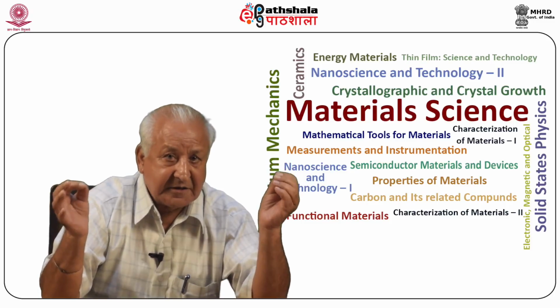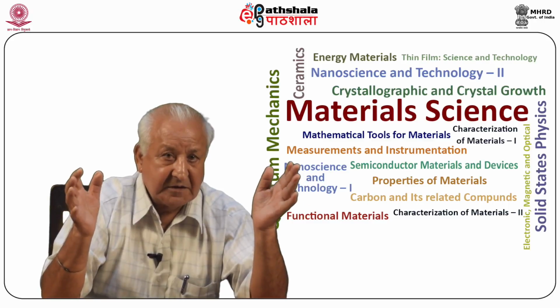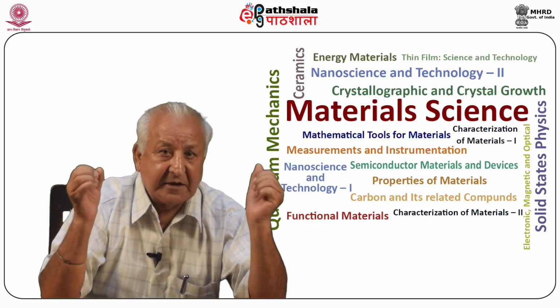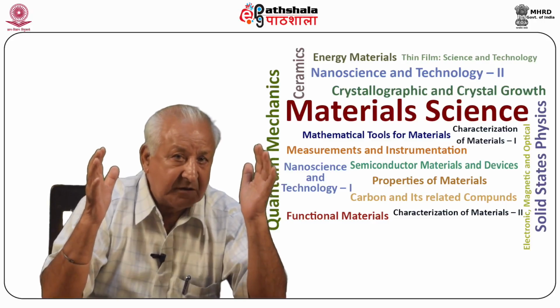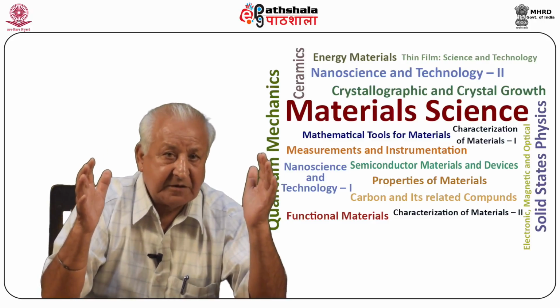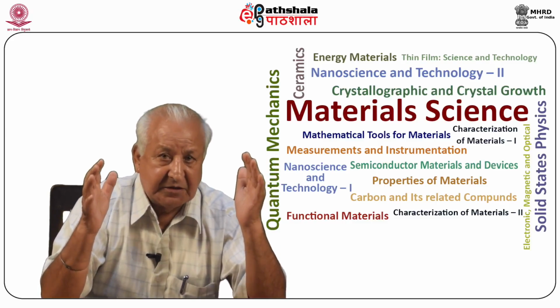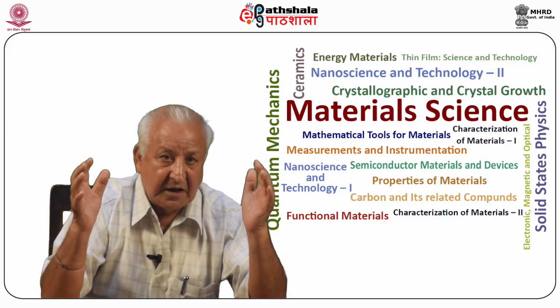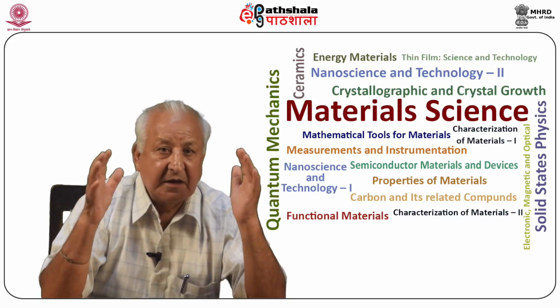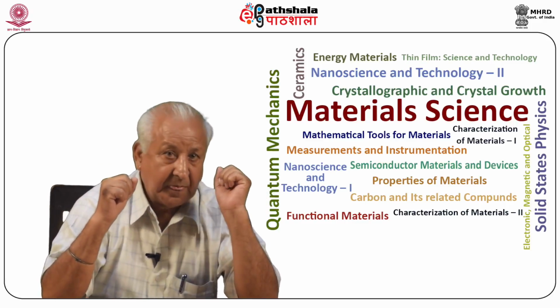Electron and X-ray detectors are positioned close to the specimen surface so that the angle of the emitted X-rays is about 70 degrees to reduce absorption effects on account of surface irregularity to a minimum. Since the EPMA is required to have high sensitivity for X-ray detection, the primary electron beam is incident normally on the surface of the specimen.